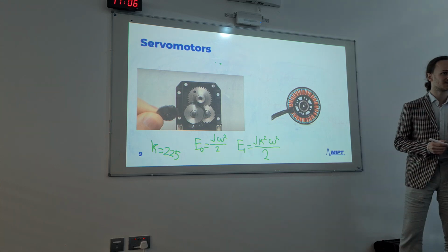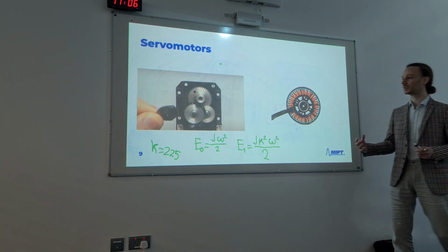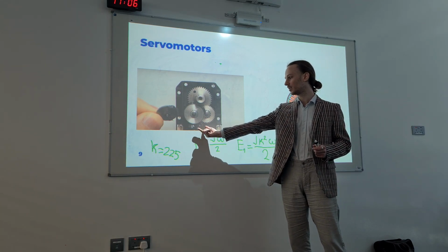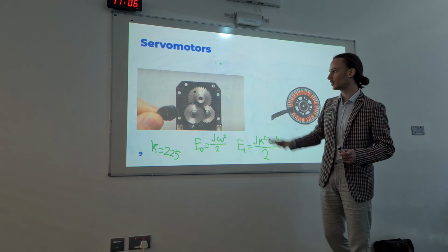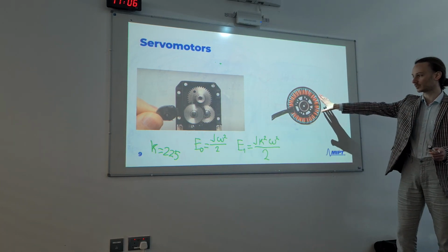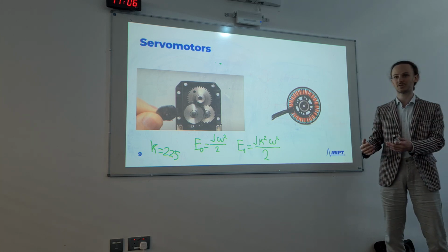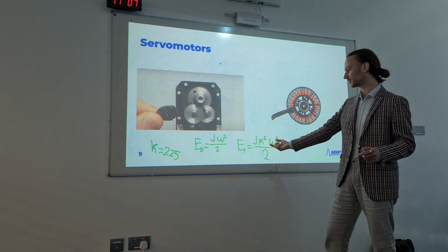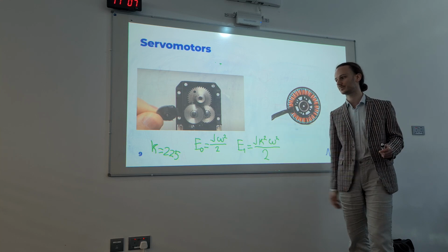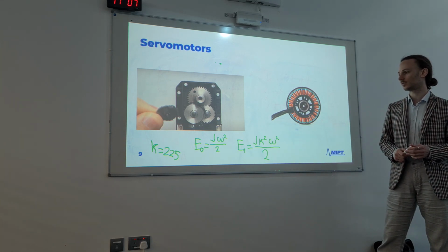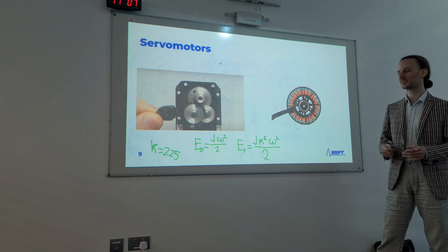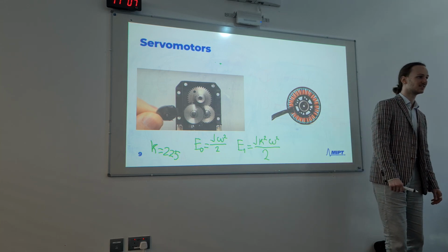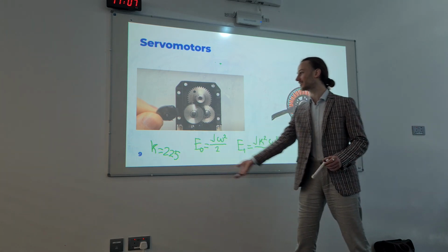The good news is that there is an alternative. Instead of using a very high RPM, rotations per minute, rotor and a big gearbox, we can use a relatively low RPM rotor like this, and just a small gearbox, maybe 10 to 1. That's much better because it will give an amplification of just 100 compared to several thousand. Oh no, it's not. I have miscalculated. It's not 4,000. It's 40,000 actually here. So it's very bad, right?